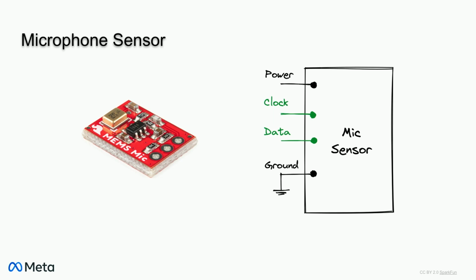In our research, we discovered that certain microphone manufacturers actually have enough internal voltage bleed from the clock signal to sufficiently power the sensor and get data off of it, even if you completely cut the power. And this is somewhat surprising, and once again we find that powering off the device is not the most secure or private option. So in this case, we recommend gating the clock or the data or both.